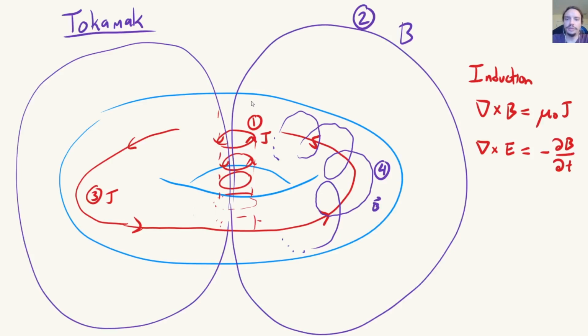Okay, I included one picture here of how that tokamak transformer works. I'm going to say it quickly, but if you're curious about this after the talk, feel free to ask questions about how a tokamak works. We have our transformer in the middle. It's a bunch of coils that are stacked together. You power them up and you increase the voltage and the current through these coils as you're operating the tokamak. That produces by induction a magnetic field that's increasing, which produces by induction a current around the torus that's increasing.